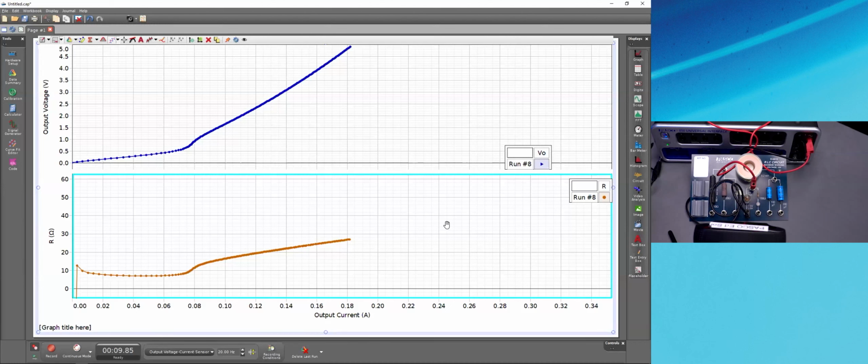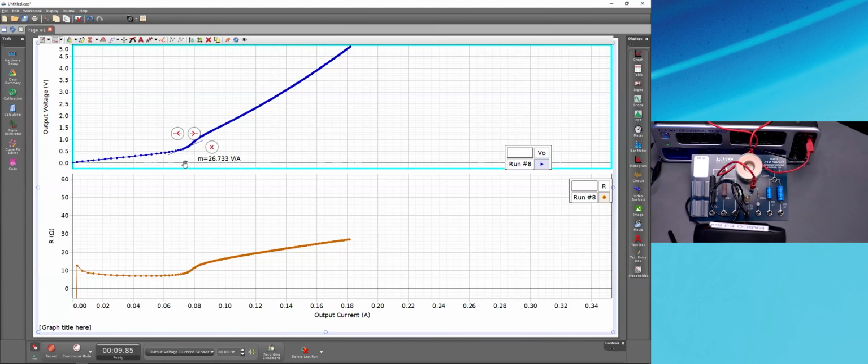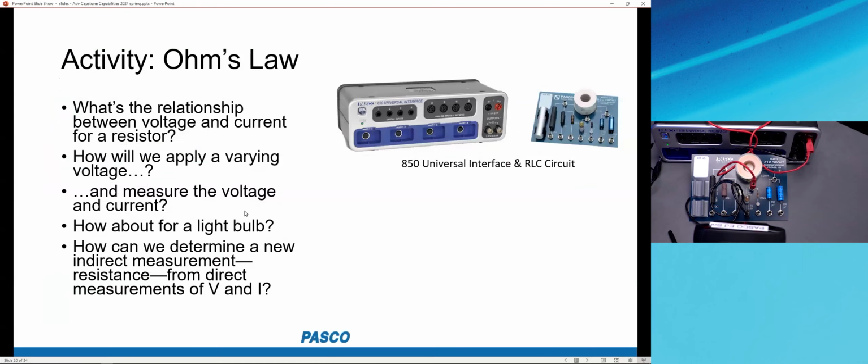So Boris notes differential versus average resistance. Yeah, if we want to talk about the concept of differential resistance, then we might, for example, turn on a slope tool to this plot of voltage versus current. And that tangent line is what some people call the differential resistance. In this case, though, we're actually looking at the resistance at a point, either by looking at that chord slope that we looked at graphically earlier, or by doing this live calculation of the resistance as the ratio of voltage to current. All right. So that's Ohm's law.